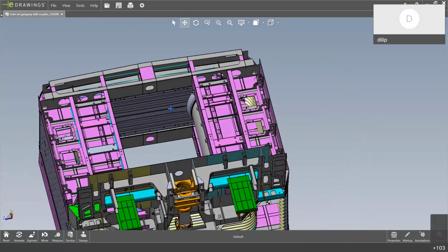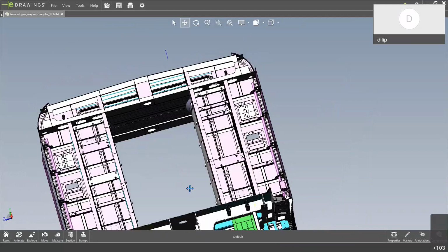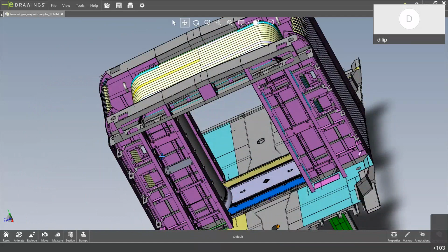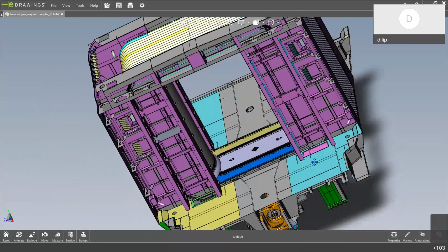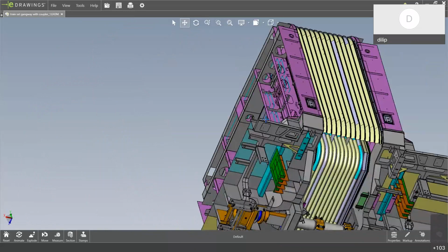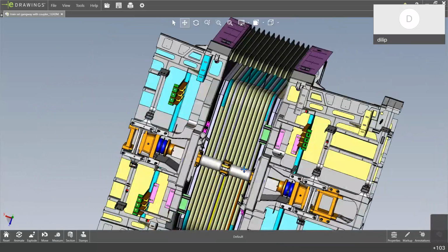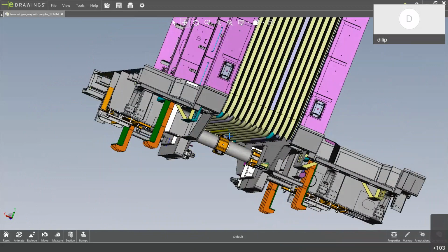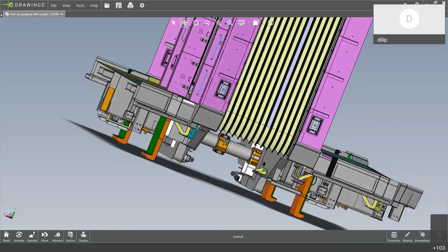This particular view, it is not there. Whatever scissor arrangement is available in the bottom of this gangway is fitted on the top of the gangway also. Another thing, I will show the coupler arrangement also, the mechanical coupler. If you see, there is a gap between the coupler and the flexible gangway. One type of arrangement I have shown in the slide, where the gangway will rest on the coupler. In some metros, like Chennai Metro, they use this, and there you may not require separate bellows again. So here, there is a gap between the bellow and the coupler.